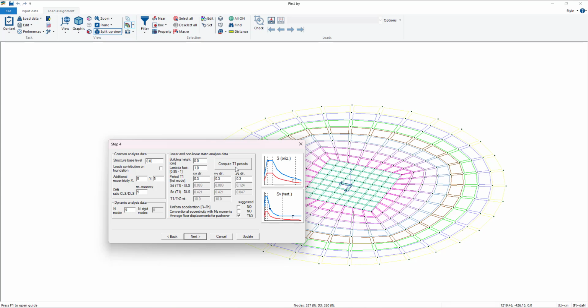To do that, the software needs some elevation structures, so some elements that are above the structural base level, because everything that is modeled above this level is going to give structural mass. Otherwise there is no structural mass in our model, like in this case.